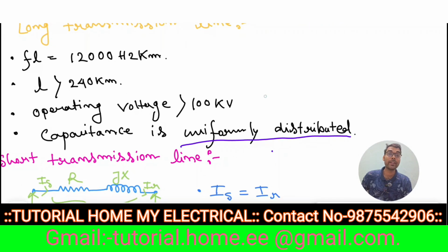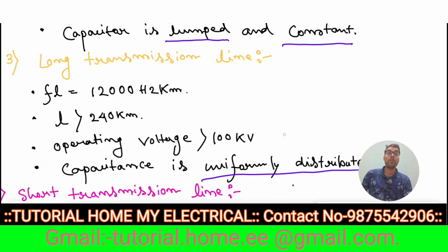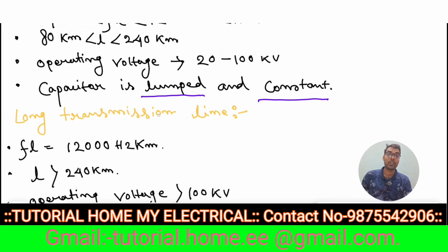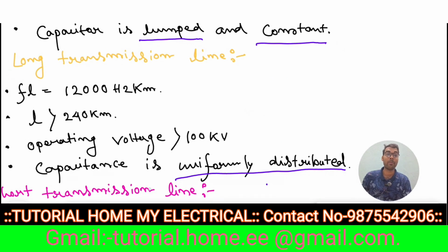Here we take capacitance as uniformly distributed. In a medium transmission line, we assume capacitor is lumped and constant, but for a long transmission line, we take capacitance as it is in the transmission line, means uniformly distributed.